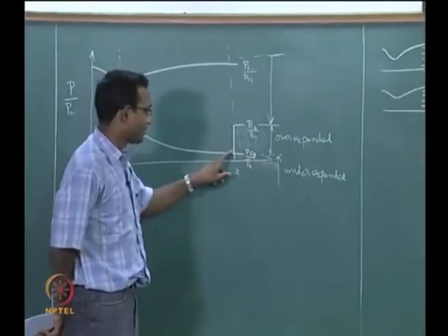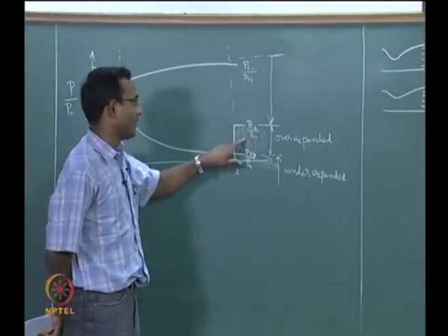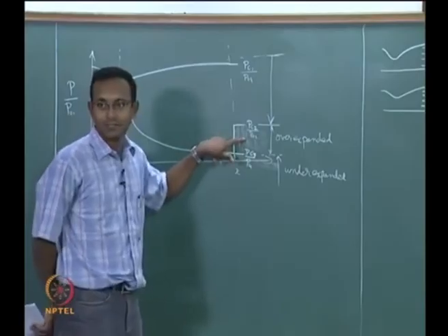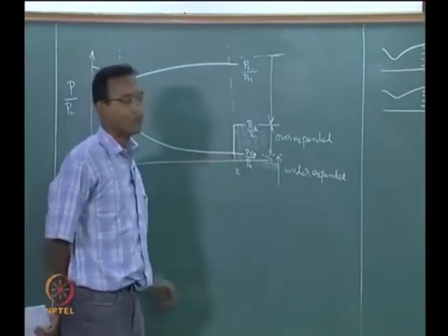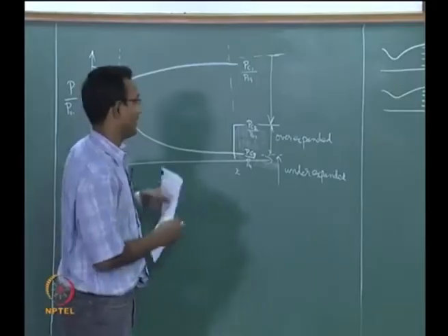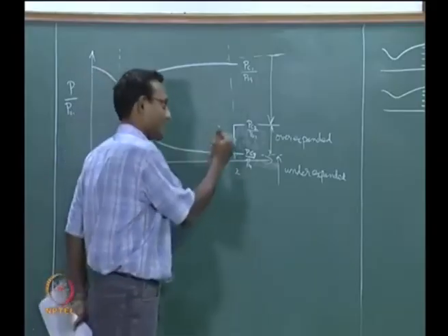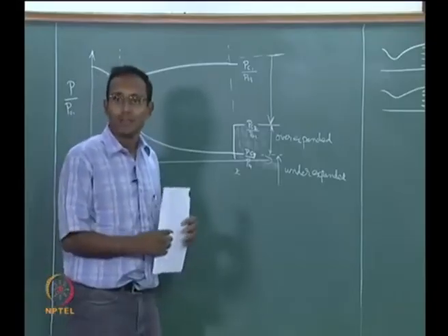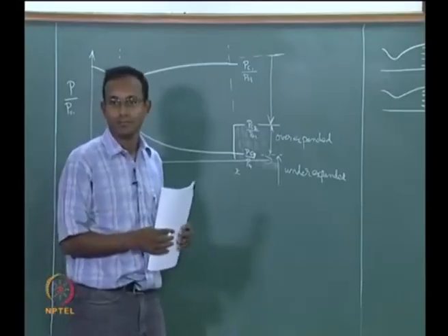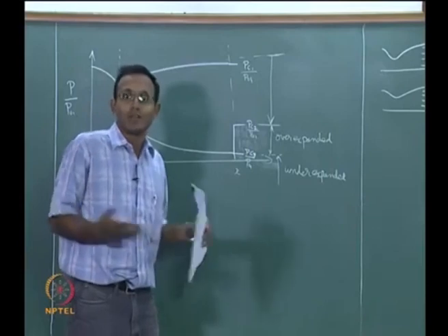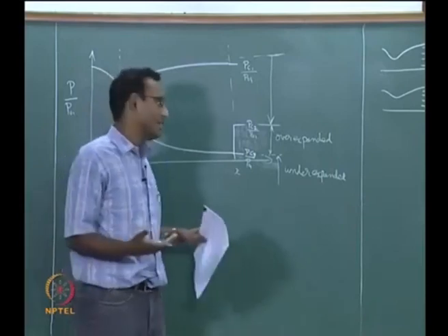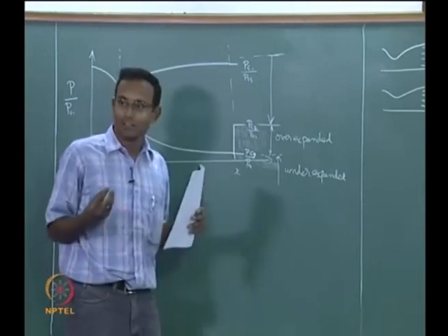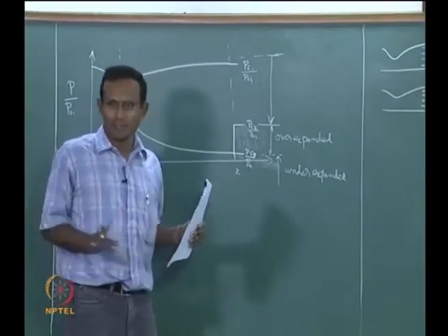I am going to say this fluid is much more expanded than what is needed for the outside world. So, currently it is an over expanded condition. That is what I am going to look at. When I look at it this way, what do I need to make the pressure go up? It should be a set of compression waves, and typically we will say that compression waves bunch together and form a shock. We will keep it that way for now.